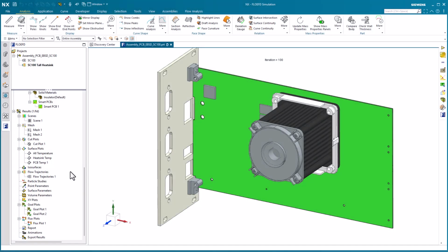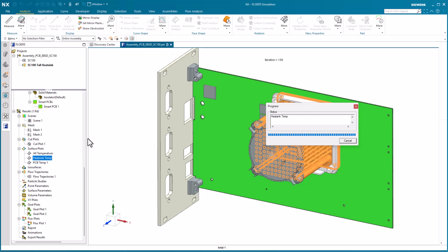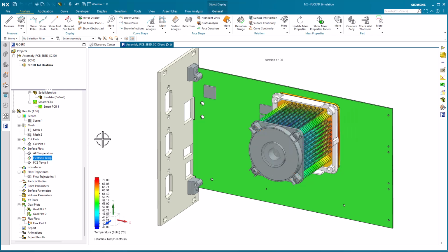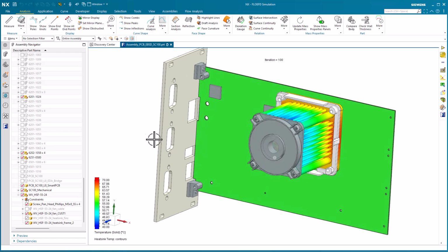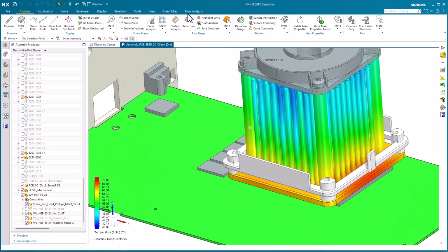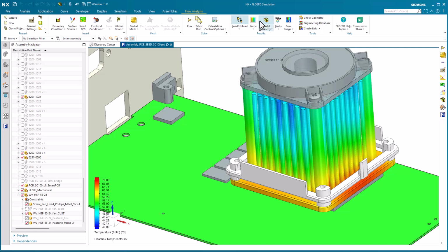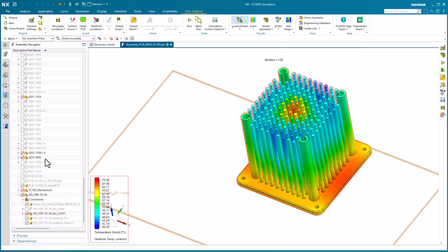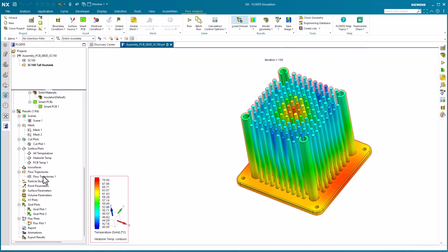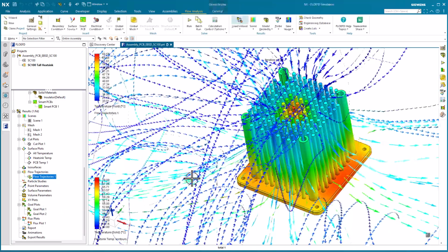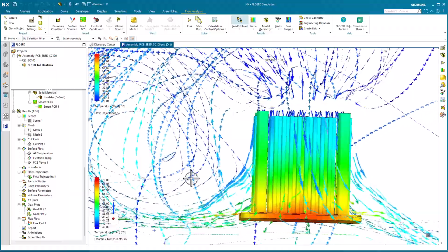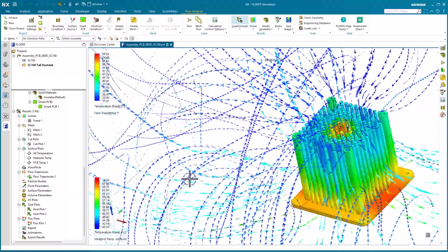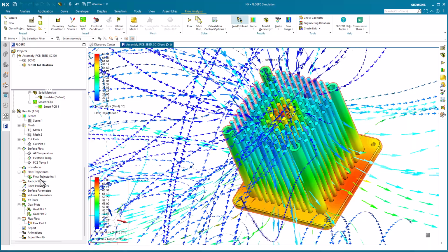The heatsink is saved, and going back to the assembly, the heatsink has changed and the fan position is updated due to assembly constraints. We've already solved the updated heatsink revision, and we can see the temperature results of the change. The flow is also updated, and we can see air leaving from lower in the pin stack. But how do we know if this design is better? What's the delta from the base case?